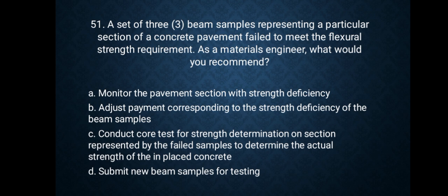A. Why is it the answer? Because DPWH Standard Specification Volume 2 specifies that the penetration grade of asphaltic material appropriate for sealing of PCCP joints is 85 to 100.